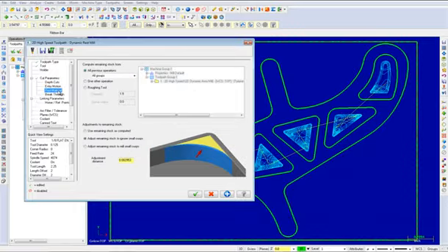This page defines how Mastercam calculates the stock model for a 2D high-speed rest mill or dynamic rest mill toolpath. You can choose to calculate the stock remaining from one or more source operations or based off of the roughing tool. Under the option Compute Remaining Stock From, enable the option All Previous Operations and enable Use Remaining Stock as Computed.